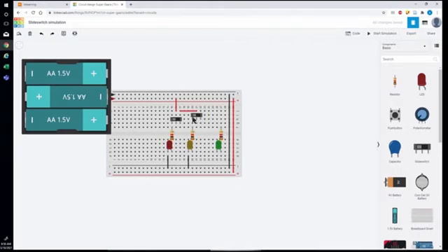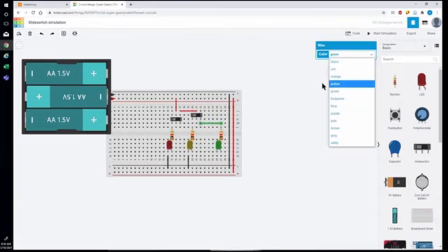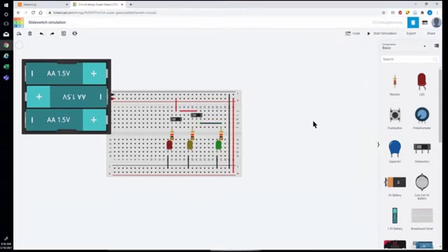And I'm going to connect terminal 1 of the second slide switch to yellow, and terminal 2 of the slide switch to green. Just use a wire so I don't have to move anything, and connect this into the ground. So if I did everything correctly, I should have a choice between a red, a yellow, and a green. So let's take a look.